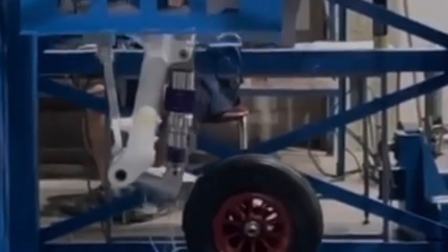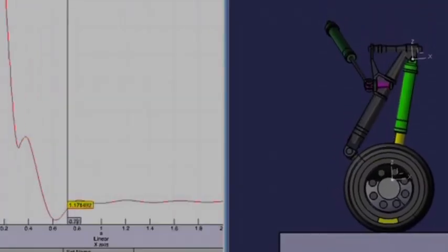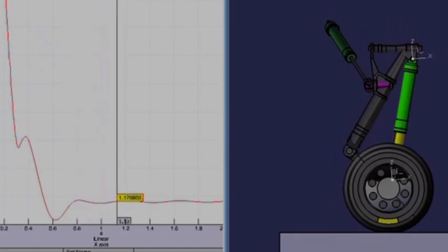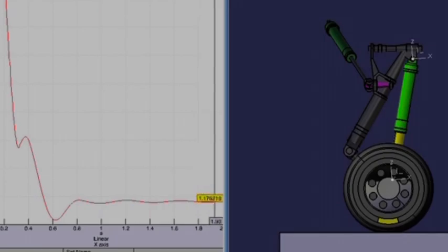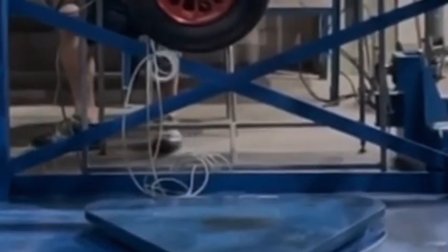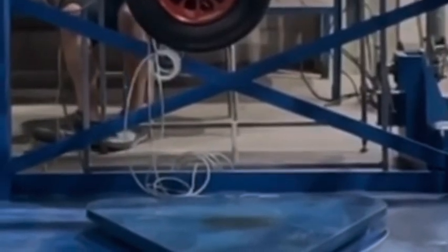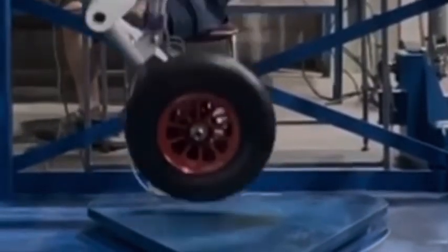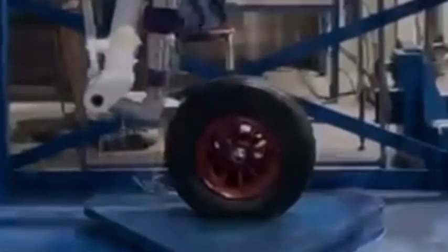In the drop test, the landing gear structure is attached to a machine or mechanism, and the machine brings the landing gear down onto a surface. The amount of force applied to the landing gear is calculated, and the manufacturer wants to make sure that there is no damage or deformation on the linkages and the main structure of the landing gear, besides other tests.